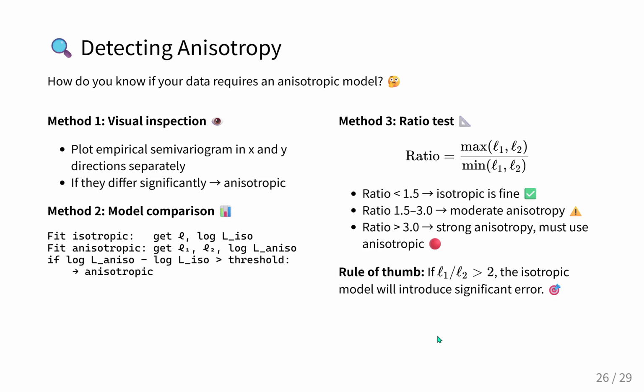If the ratio is under 1.5, the grain of the chip is so minor that the traditional simple isotropic model is perfectly fine. You don't need the computational heavy lifting of the 4-parameter model. But if the ratio is between 1.5 and 3.0, you have moderate anisotropy. Right. And if that ratio is greater than 2, the source sends up a massive red flag. Sticking with the isotropic perfectly square model will introduce significant critical error into your timing margins.